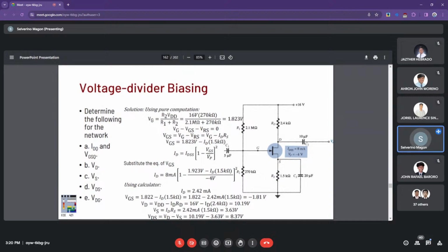Right? So in DC, inductor is shorted, capacitor is open, but in AC or higher frequencies, it's the other way around. The inductor acts as an open circuit or a high impedance component, while the capacitor acts as a short or a low impedance component, allowing the AC signal to pass through to the VO right here. So that's some snippets of the amplifying action in this configuration.